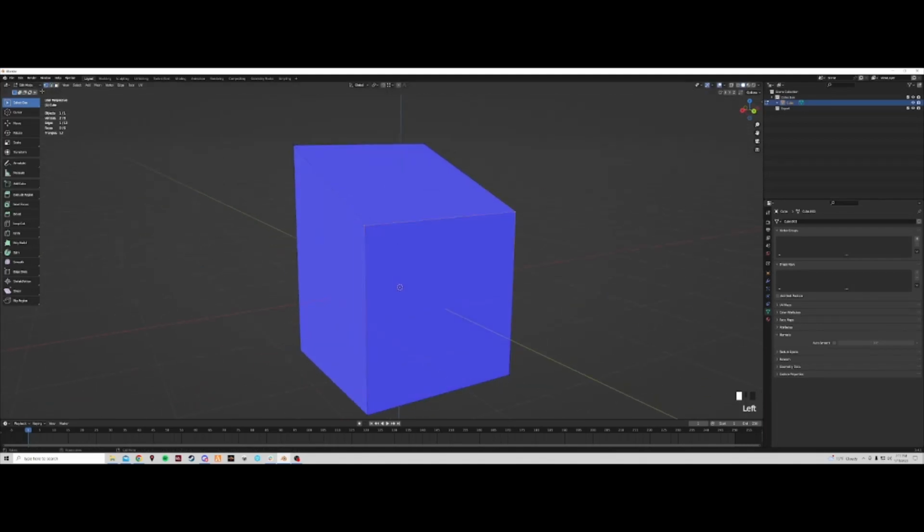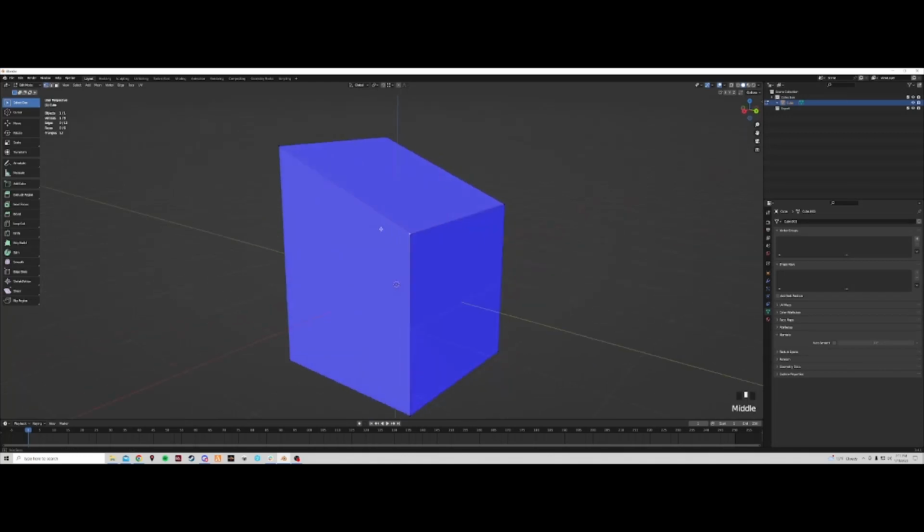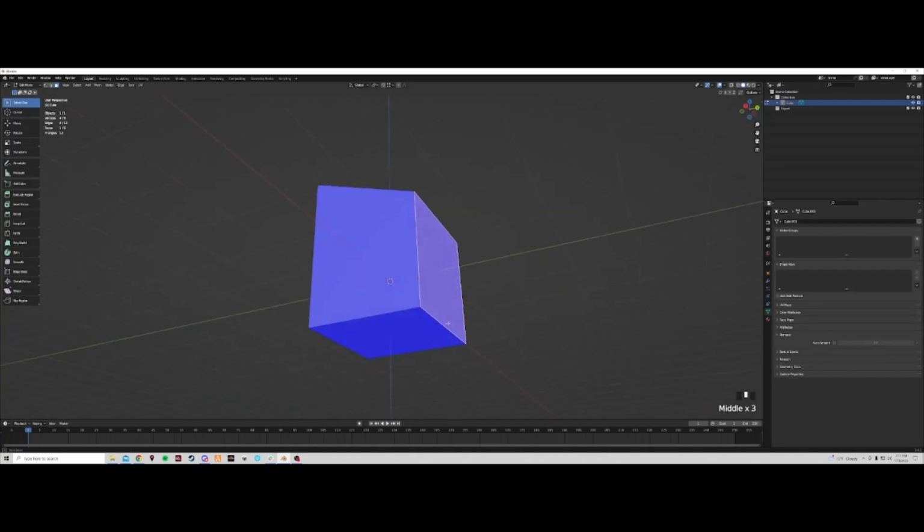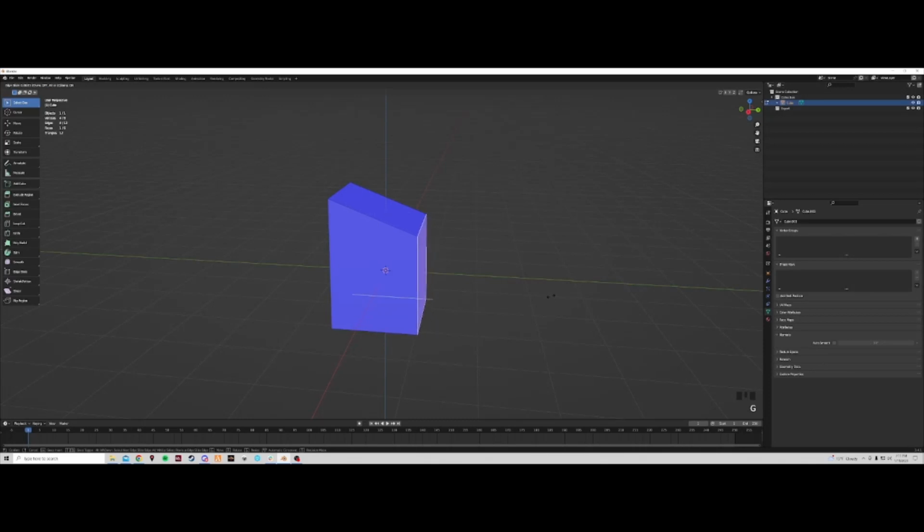You can also edge slide vertices. So vertice, there's 3 edges attached to this one. I can slide along that edge, or this edge, or this edge. Whichever edge I want. Now you can also edge slide faces, and it will slide along all edges attached to that face. And if you go the opposite way, it slides on its own edges and becomes smaller.